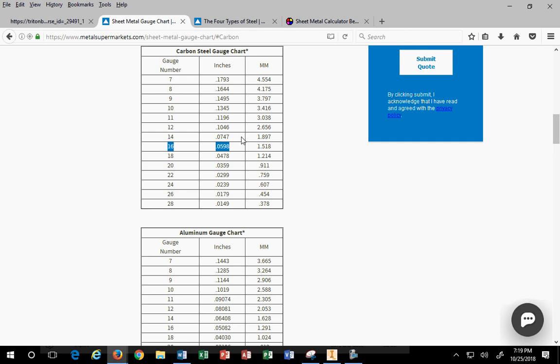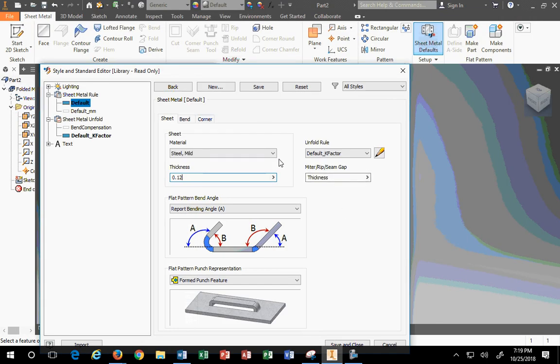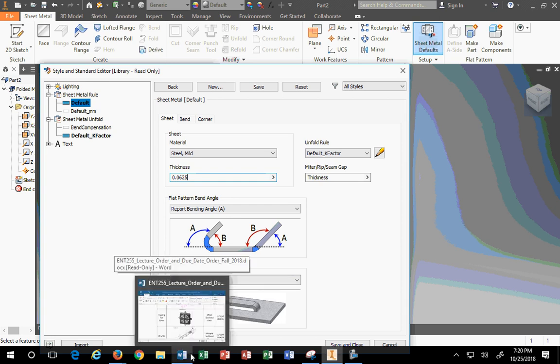Here in an academic setting, everything's theory. So we're operating on theory. So we're going to theorize that we're going to go with what the handout told us, 0.0625, which to me is like, yeah, right. But I'm going to use it anyways. Okay? I'd want to know. I'd be miking several different inventories of material to verify what really do we get in the company if I was in the field. So here, I'm just going with what I'm told. In reality, I don't ever want you to go with what you're told. I want you to check the material you're using.